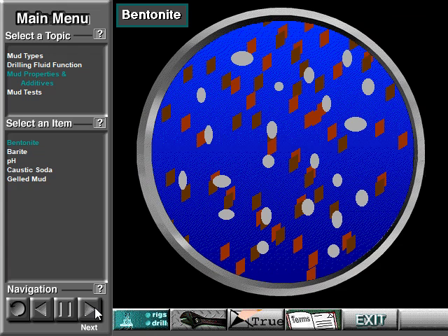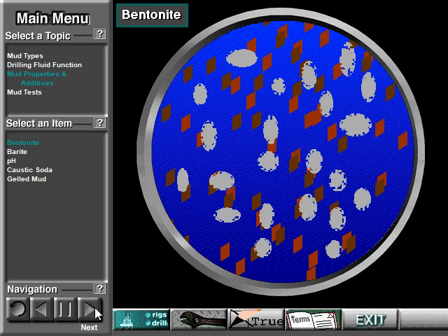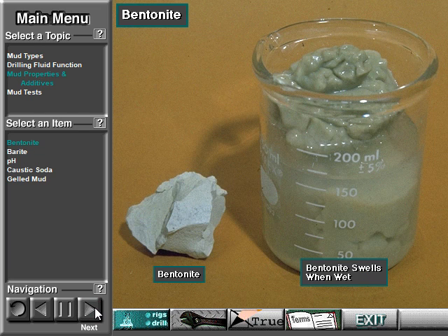In water or oil-based drilling mud, crew members usually add a clay called bentonite or a similar mineral. Bentonite swells in water. Therefore, it thickens the mud, gives it viscosity to help clean the cuttings from the hole and provide other desirable properties.